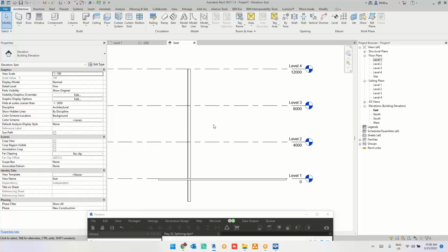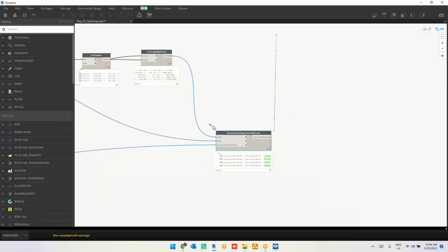Did you see this now? And you can ask me why I can see the additional point here. From here to here, it's 1, 2, 3, 4. Because we are using a base offset of minus 2500. Generally, the columns have to start at 0, and below the column we'll have some foundations.